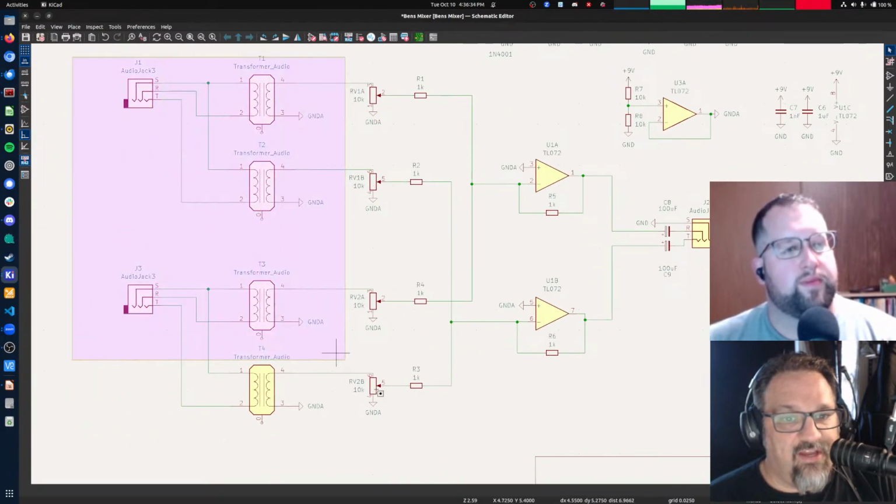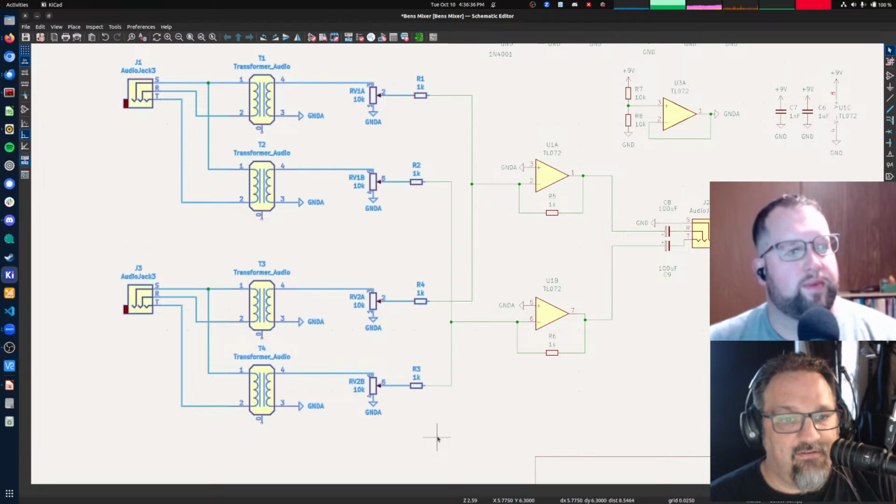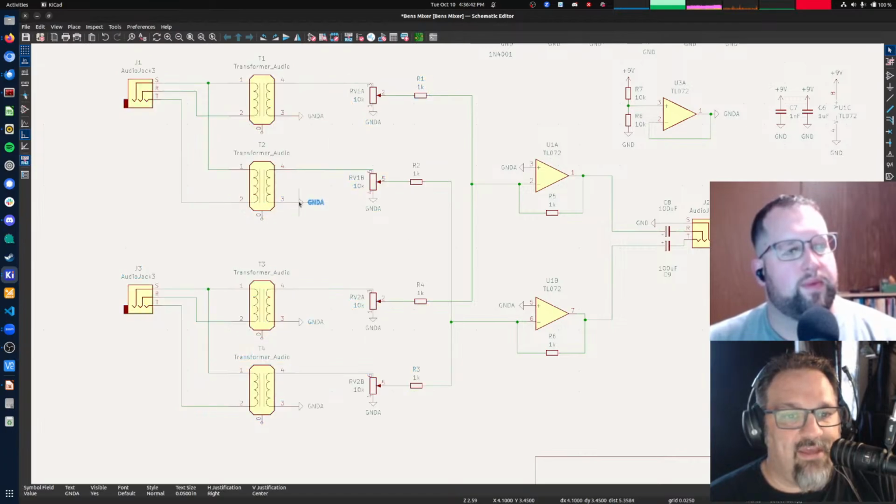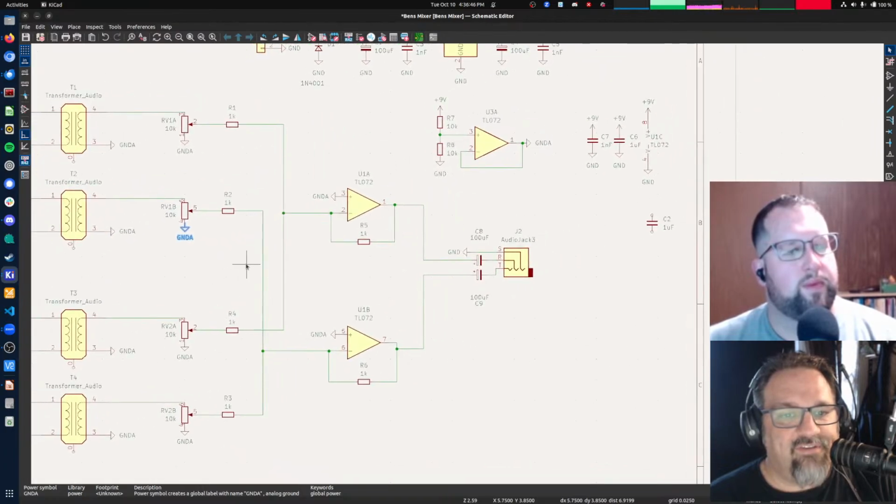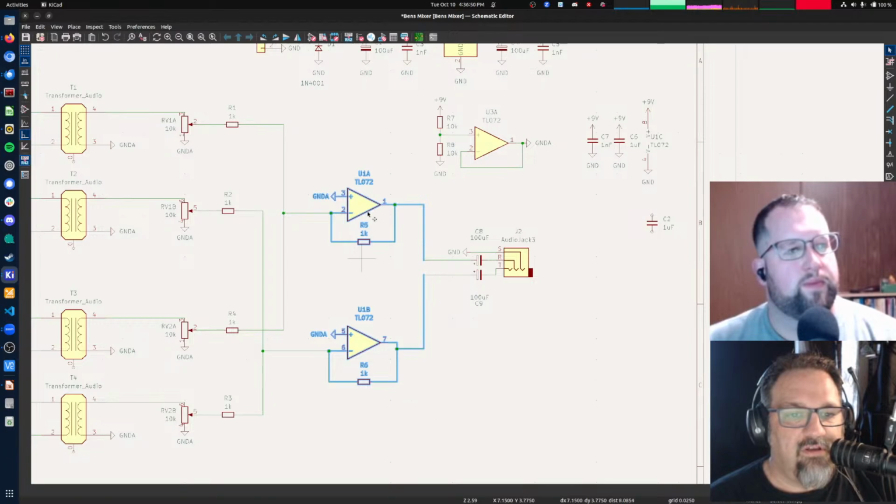So this over here is what you already had. We haven't changed any of this, except by renaming this common node that you had. What we have done is we have inserted the op amps here, one per channel. We're using them as summing amplifiers to sum the currents coming from all these different input channels.